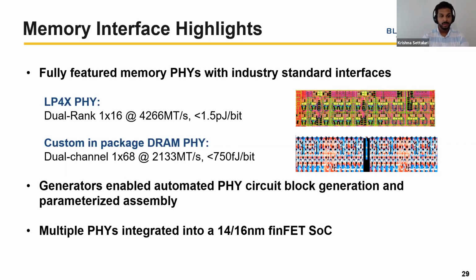And I'm excited to say that this actually does work, silicon proven. The memory interfaces were integrated into an SoC, and the full SoC, along with the interface, showed successful operation. It's also worth noting that for this particular project, our team did a tremendous amount more than just the memory interfaces. We actually had generators for PLLs and DC-DC converters as well. And we were able to tape this out with the resources I believe that we had, partially because of the benefits of the generator flow.